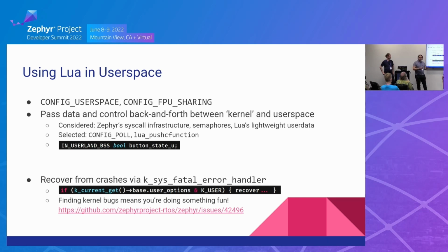There's an interesting challenge here. If you're going to run more than one of these tasks, which we do, you have to decide how you're going to map memory partitions to tasks. We ended up doing it so that all the tasks run in the same memory partition, and if any one of them aborts, then you probably have to consider the whole thing contaminated. That's a trade-off about how much overhead do you want on switching.